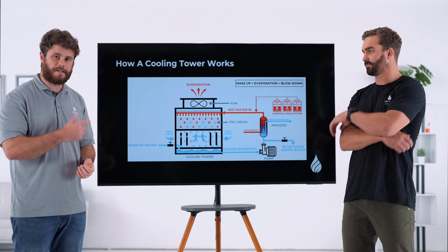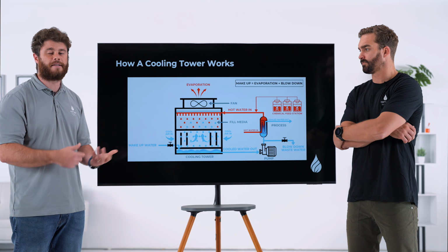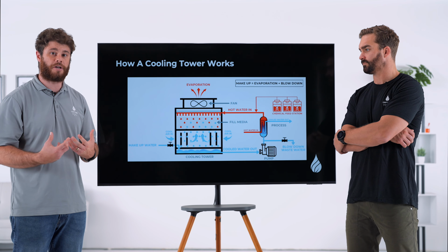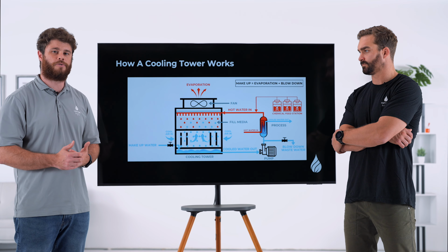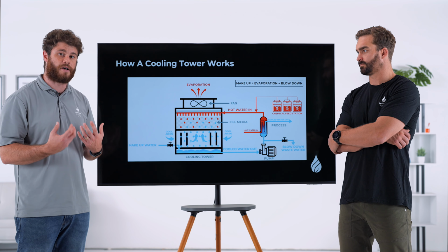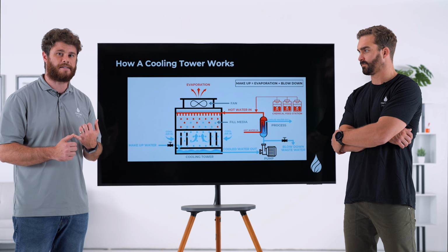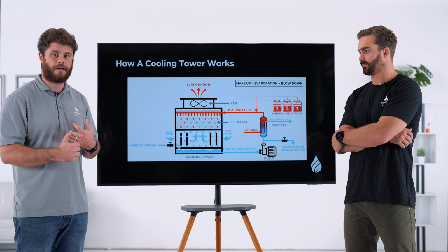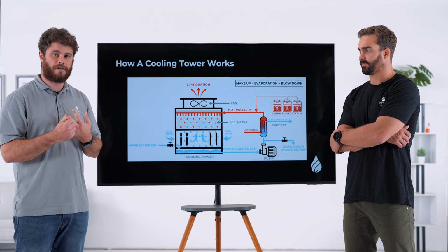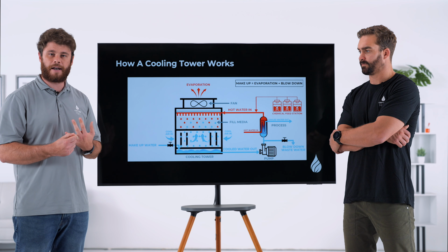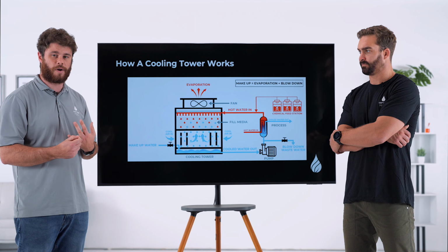Now this process continues and continues as the tower operates, evaporating just that pure water, just that pure H2O. All the minerals we can't see with our eyes, the dissolved solids in the water, such as magnesium, calcium, and silica, are concentrating up in the water. They're not evaporating. And as this occurs, your system is going to start being exposed to adverse effects, namely scale buildup, corrosion, and bacteria.